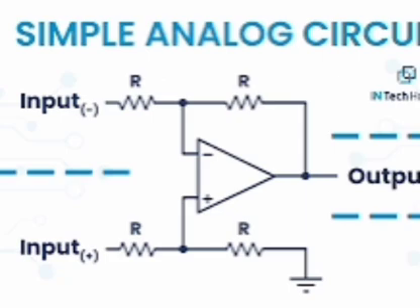Full wave center tap rectifier. Average value of current and voltage: IDC equal to 2IM by pi, VDC equal to 2VM by pi, ideal case. RMS value of current and voltage: IRMS equal to IM by root 2, VRMS equal to VM by root 2, ideal case. For practical case, IM is replaced by IM dash, where IM dash equal to VM, numerator part VM, denominator part RS by 2 plus RF plus RL, and VM dash equal to IM dash into RL.